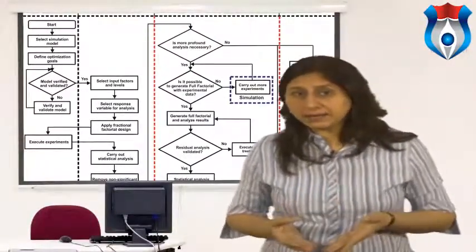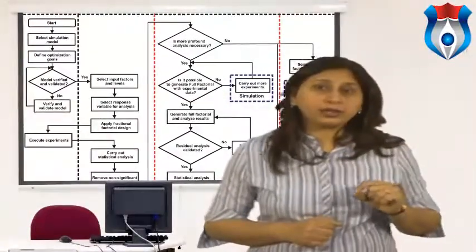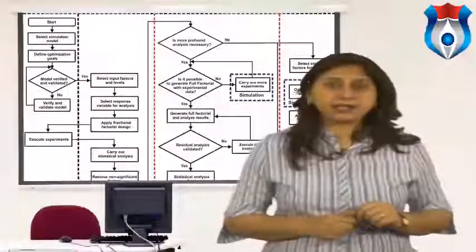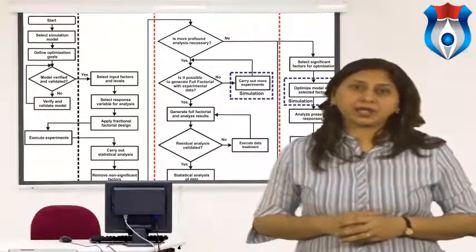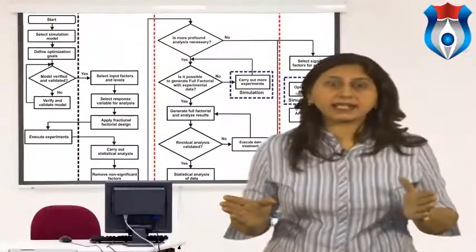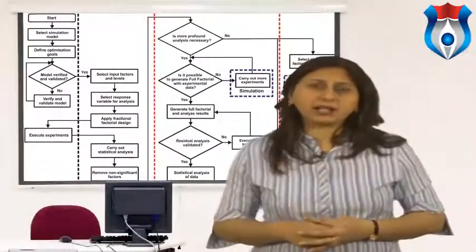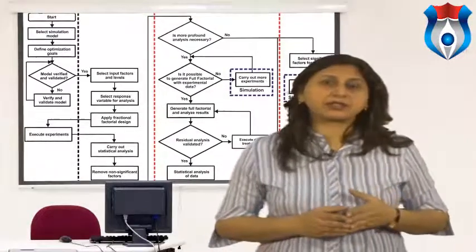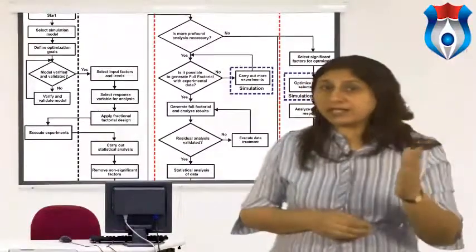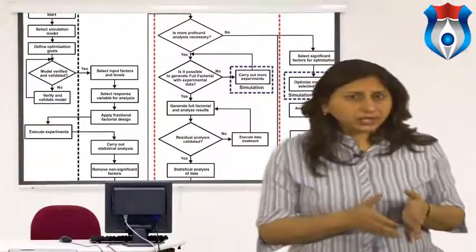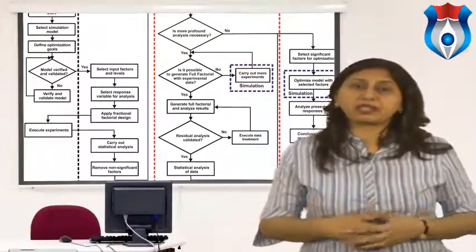Example, processing times, arrival rates, etc. Another key point is to ensure the model is valid, that is, its behavior mirrors that of the original physical system. For systems that do not exist yet, because simulation is used for planning them, this is especially hard. Insufficient validation and verification of a simulation model is one of the top reasons for failing simulation projects. The consequence is false results, and this lessens the credibility of the method in general.